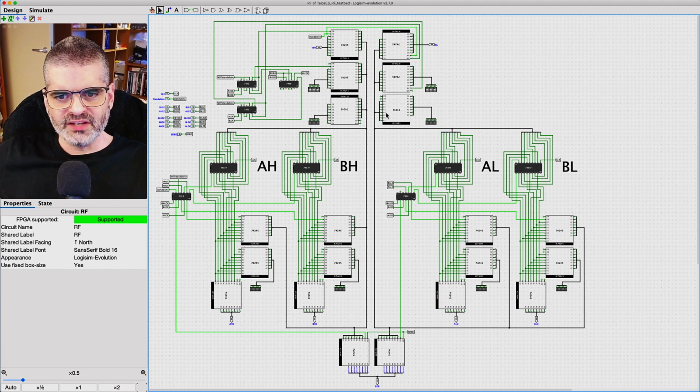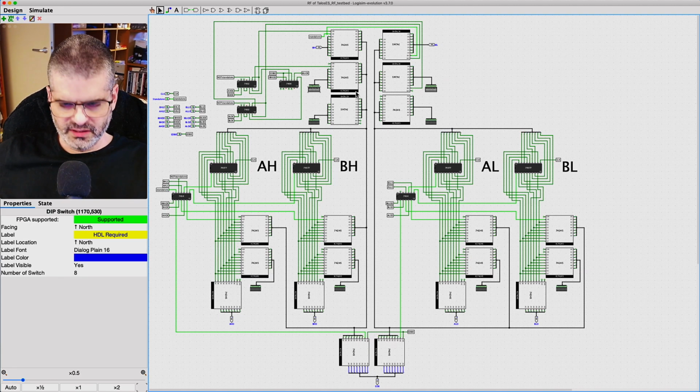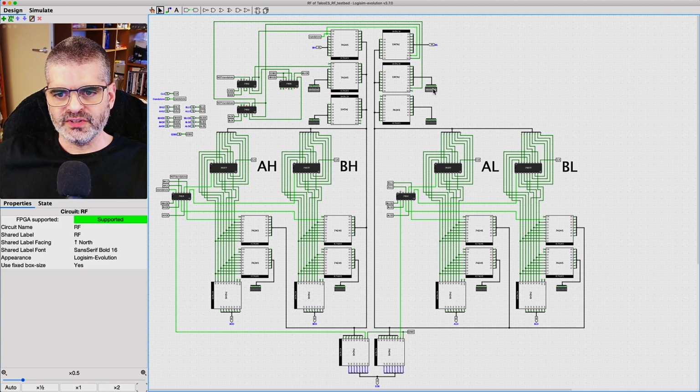So we can visualize the contents of the bus next to the contents of the registers. So these two only drive LED bars, no other functionality. And then I added two dip switches, here and here. And of course we need a buffer to drive the contents of the dip switch into the buses. So we have the dip switch for the high bus, goes through this buffer, and here the dip switch for the low bus goes through this buffer into the low bus.